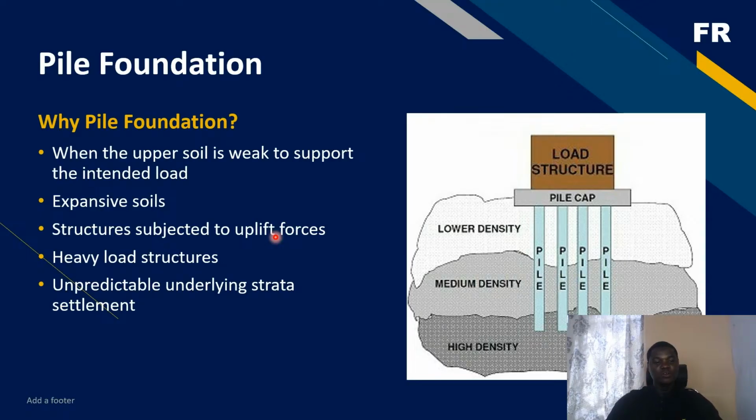So for heavy load structures like bridges, even though in some situations a shallow foundation can be enough to support some kind of bridge, generally we employ deep foundations. And apart from the structural advantage, we also have the environmental advantage. Heavy structures like dams and bridges are usually designed to last 100 years, 200 years sometimes.